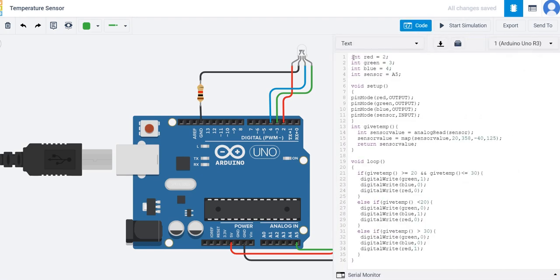I have created some variables to store the LED pin numbers. Why have I done it like this? For example, I have written the code, and I want to do a certain voltage operation on pin number 2. Then for some reason I want to use pin number 2 for some other thing, and I want to use pin number 10 or something like that. Then I have to change this pin number 2 in each and every code segment, and this will become a very big problem.